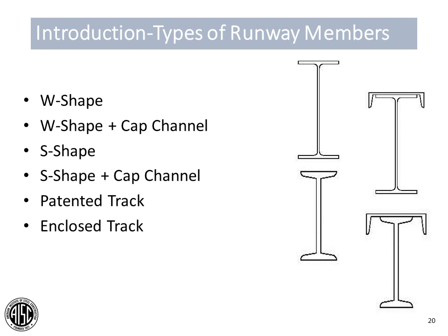There's also a number of different types of runway members that you can design. Typical runway design would utilize a wide flange shape. A couple shortcomings on these wide flanges is they tend to have, as their name would imply, a wide flange, but it is also a relatively thin flange. That causes local flange bending concerns in the bottom loaded flange of the runway member.